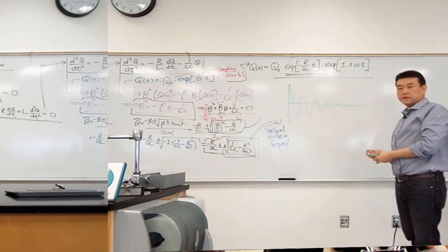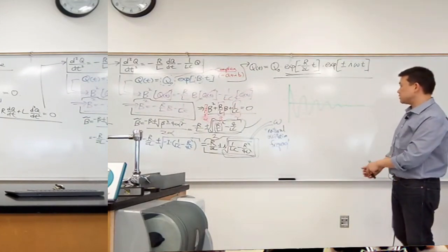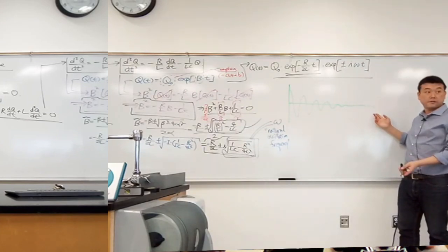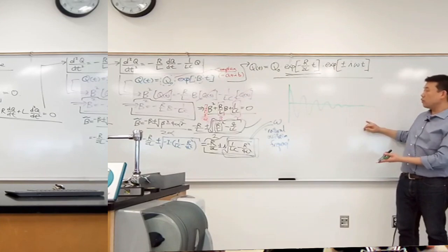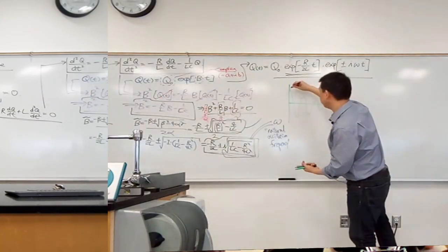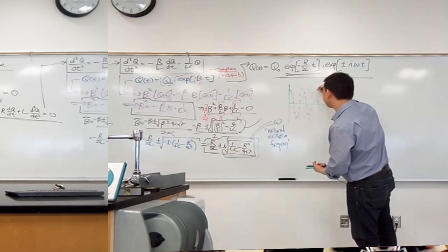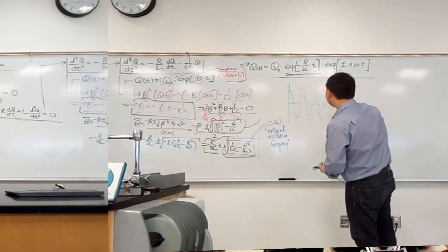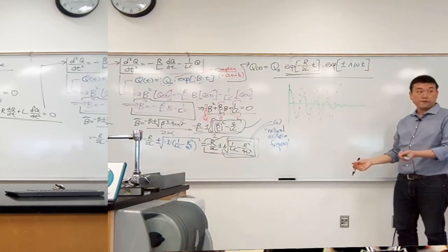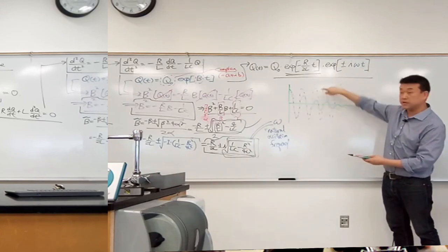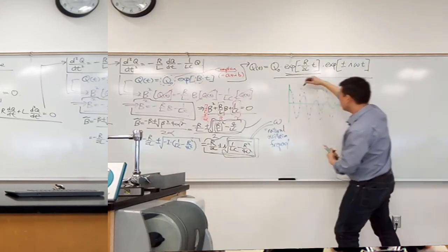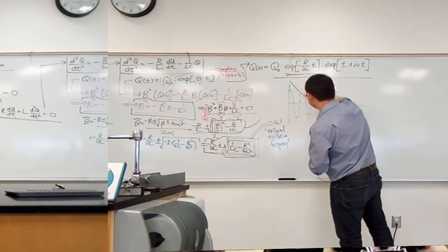The envelope is this. When we say envelope, what we mean is we imagine this entire form as a result of a product. A product of an oscillatory function, the actual sine wave, or in this case cosine, whose amplitude is not changing. And you imagine factoring out this variation of amplitude into a single non-oscillatory function that you multiply to this oscillatory function. That's what we mean by envelope. It's because that's sort of what it looks like. This is the envelope of this function.